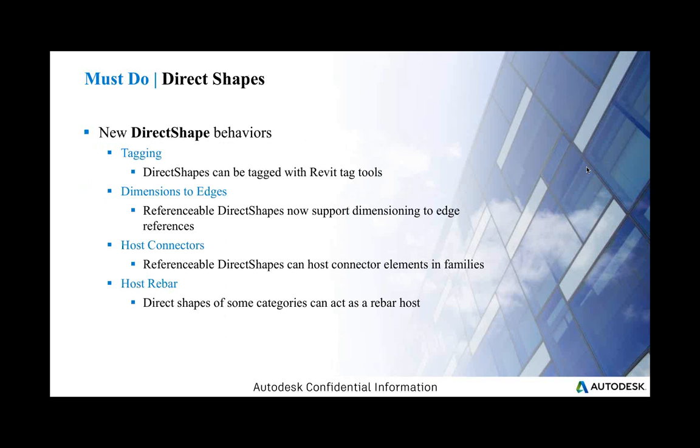A very exciting area that was introduced two or three releases ago with great success is the direct shape element. The possibility to introduce almost arbitrary geometry into the model directly without having to go the roundabout way of defining a family and placing an instance for it. This was used especially strongly by the IFC import, but it's very, very useful for all kinds of functionality and especially for many add-ins.